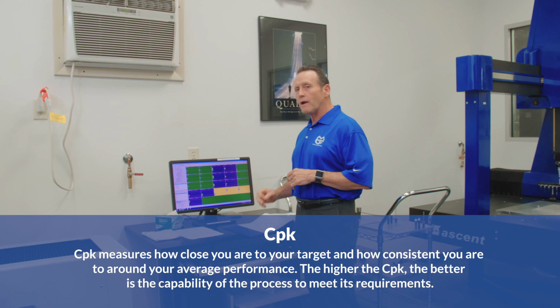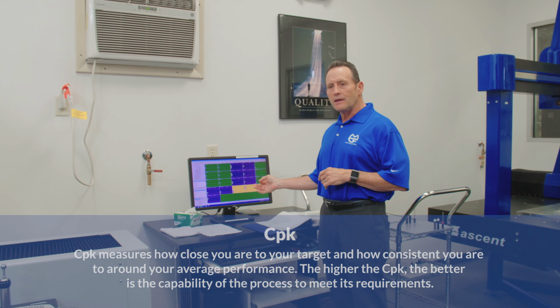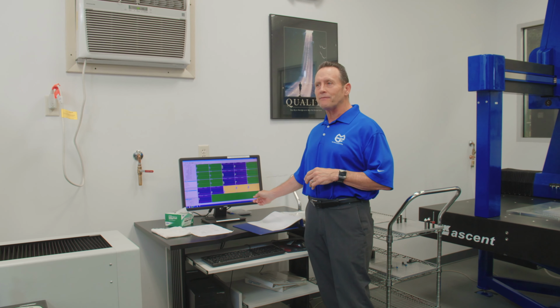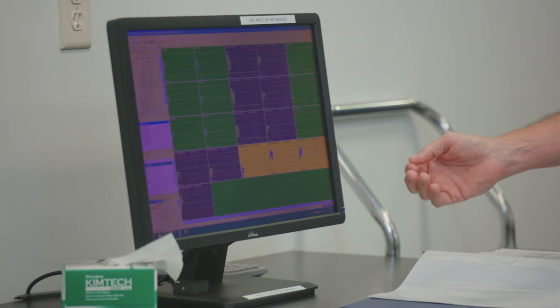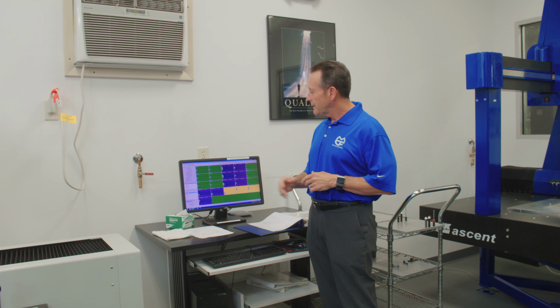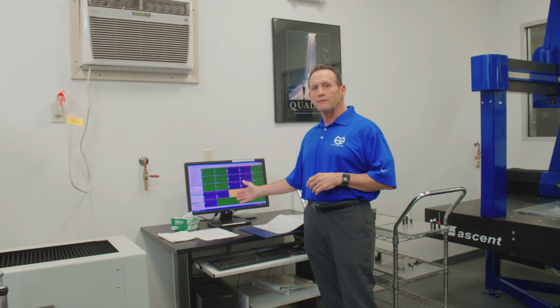The yellow means we're outside our control limits. The control limits we set in our parameters are essentially 75% of the spec limits. That's alerting the operator that he may need to take additional action, which includes additional inspections, or getting an engineer involved to help solve a problem that may exist. We don't have any red, but if it was red, we would have a non-conforming condition.